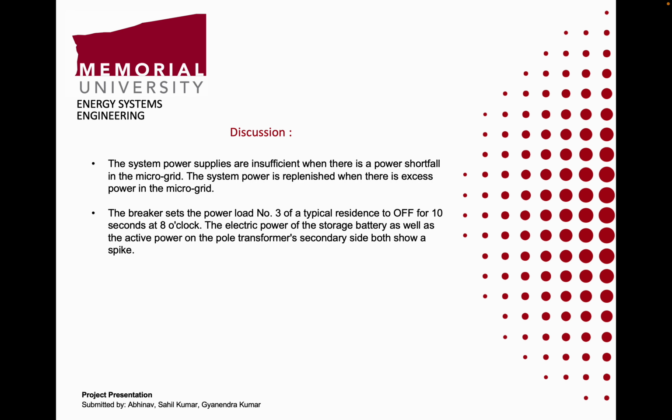Thank you, Sahil. My name is Gyanendra Kumar, and I am going to cover the last part of the project, which is the discussion and the conclusion. The conclusion of the project is that when there is a non-uniform load pattern, we should size the battery instead of the entire PV system, because most loads vary only for a short period and are constant for the rest of the time. It is preferable to size the PV system rather than the battery system in a system where the entire load pattern is consistent, where the load does not fluctuate over the typical time period.